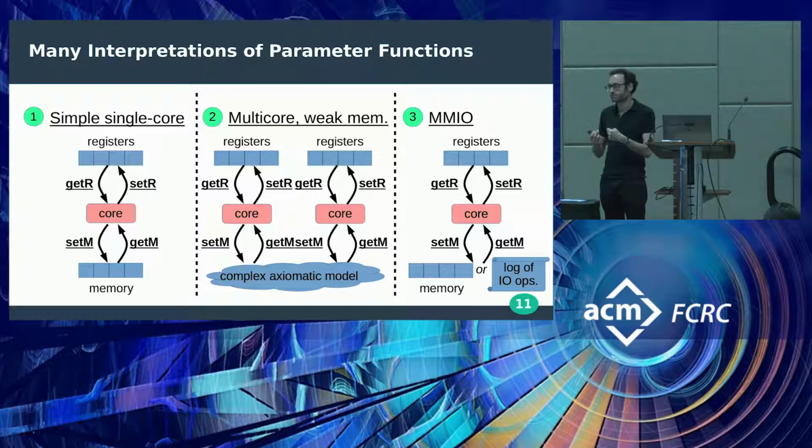And when we perform a read operation on one of these special addresses, we actually non-deterministically choose what value is found in that address, and we add to the log a record of which non-deterministic choice we made. But again, the basic instruction definitions are independent of these kinds of complications, and yet we can use them to describe MMIO as the unifying way that our processor can talk to the rest of the world.